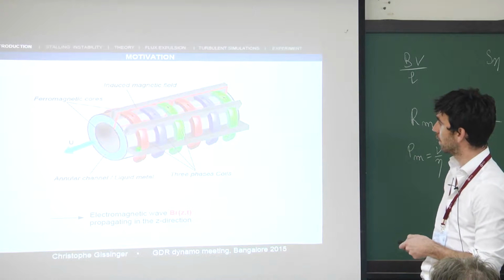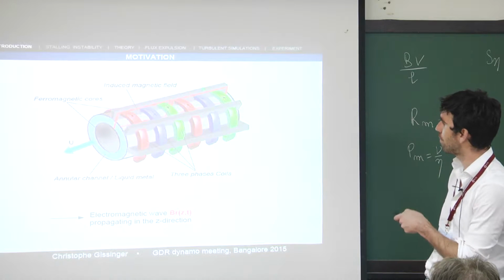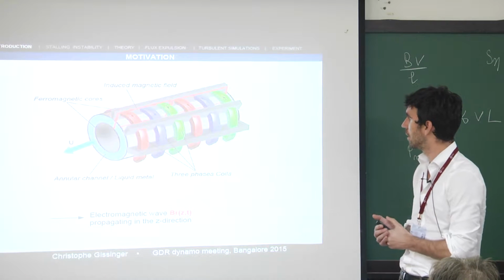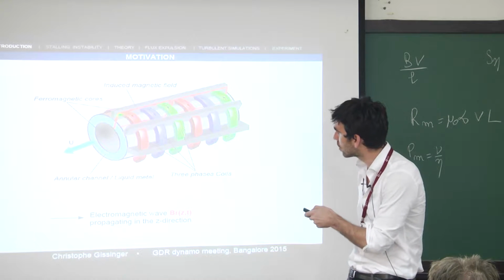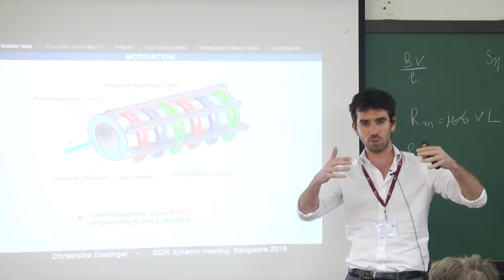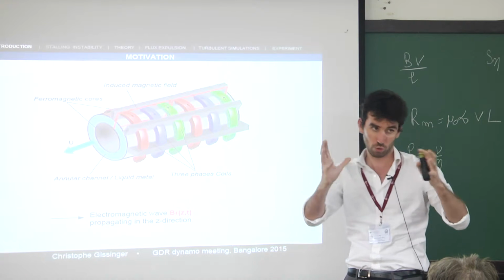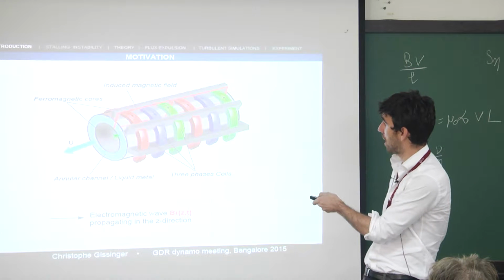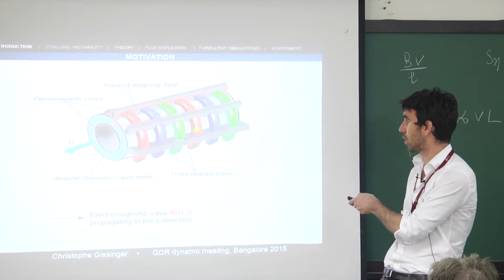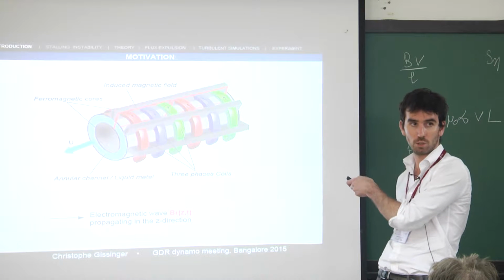the system, you have on the external cylinders some series of three-phase electrical coils and some ferromagnetic parts I will not describe here. The main idea, it's what I try to draw here, the main idea is that using these coils, you generate a very strong radial magnetic field inside the gap. Then by playing with the polarity of the coils, this radial field will have some sinusoidal dependence in Z, and it will propagate in the Z direction.